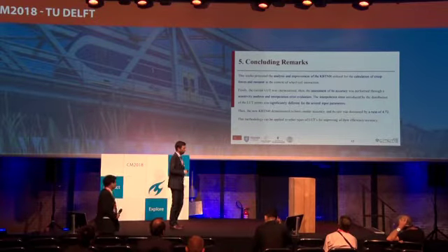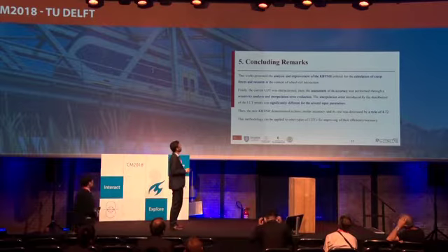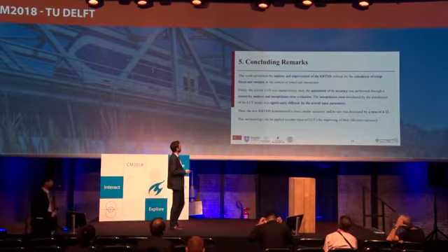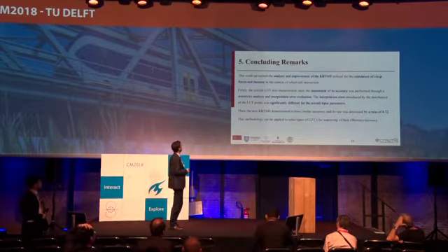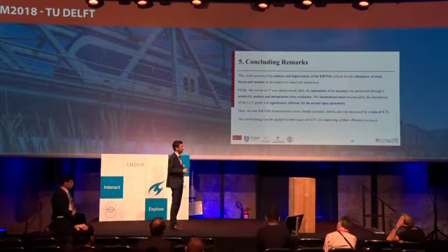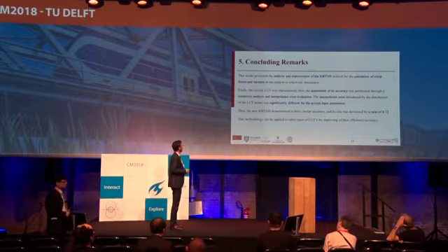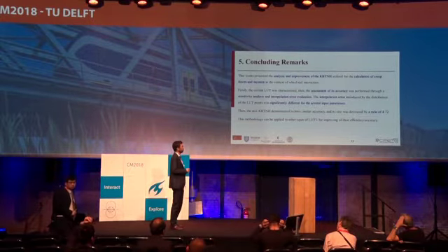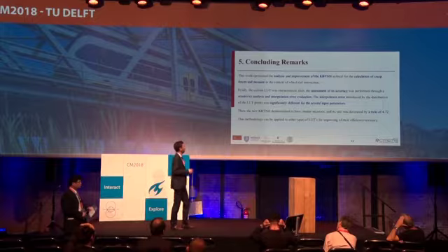In this work, an improved lookup table for non-Hertzian calculations of creep forces and moments was presented. This was supported by a sensitivity analysis on the effect of different parameters. We were successful in reducing the size of the table by a ratio of nearly 5, with similar accuracy to the original one. The next step will be to reintroduce an increase in size to obtain a better accuracy.